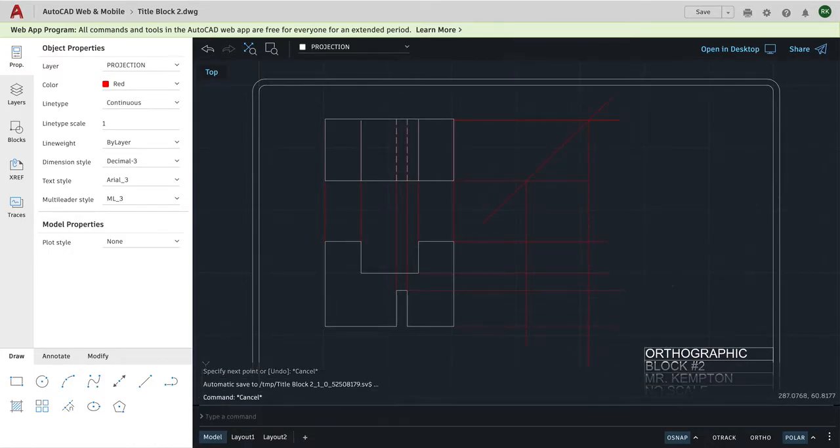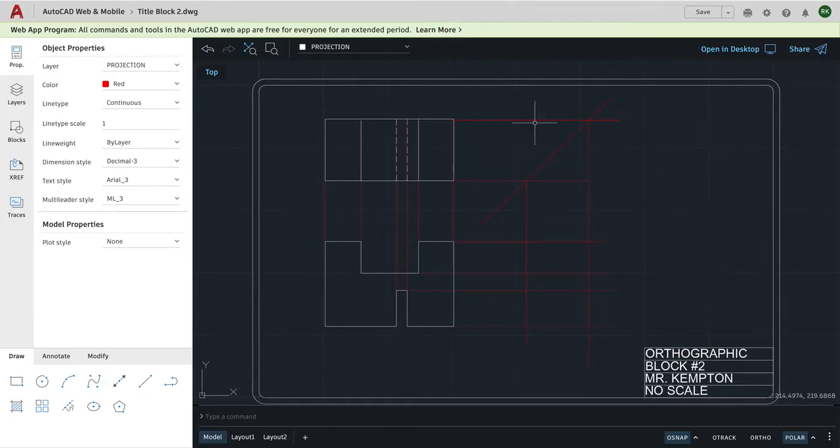Okay, so please make sure that the top of this will be your last projection line on the right. And the bottom of this will be the first projection line on the right. And if you have any other features in between here, which you will see in object number 3 and possibly 4, they're going to fall somewhere in between these lines. So please pay attention to where these stop. So I'm now going to jump back to finish this up.